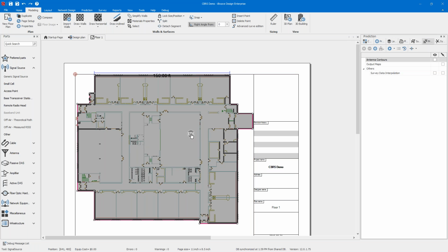And if I'm thinking as a Wi-Fi designer, I would need to put them in rooms and stuff like that. If I'm thinking as a DAS designer, I put them in corners. The thing is that cellular is not like Wi-Fi. You don't need to contain the signal as much as you do for Wi-Fi. This is because in Wi-Fi, if I have an access point here, the waveguiding effect will make the coverage go all the way down this hallway, all the way down this hallway. A client here cannot hear the client here. Since it's listen before talk, it may cause the hidden node effect.